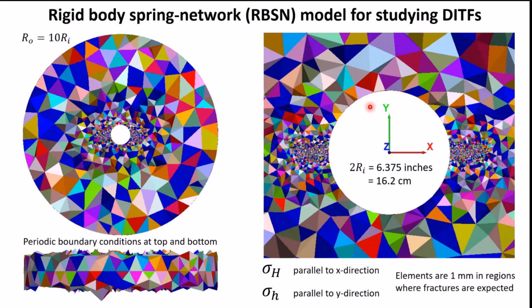Well, no, I'm just having a high resolution in the area where I expect the fractures to propagate, but there's nothing predefined. You can set the tensile strength of the bonds. What you can't set is the fracture toughness. The fracture toughness is an emergent behavior. I haven't shown that here, but you can do lab tests with pre-existing cracks, and determine the fracture toughness like that. This is with rigid block modeling.